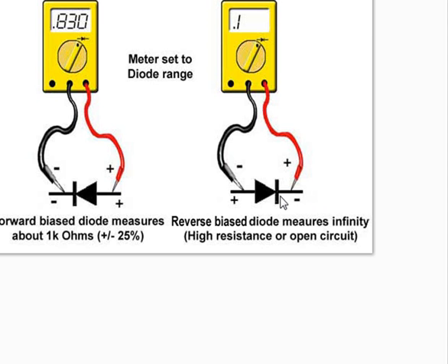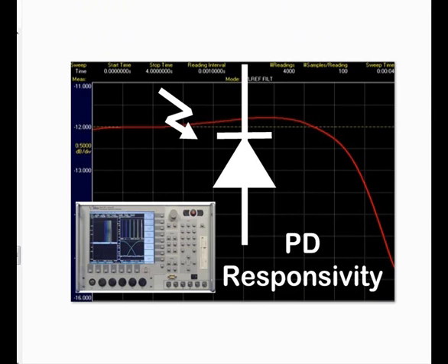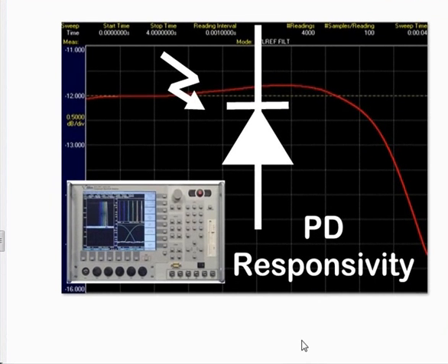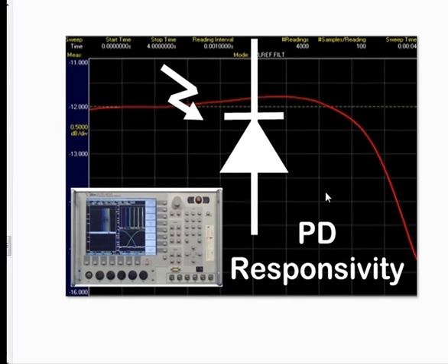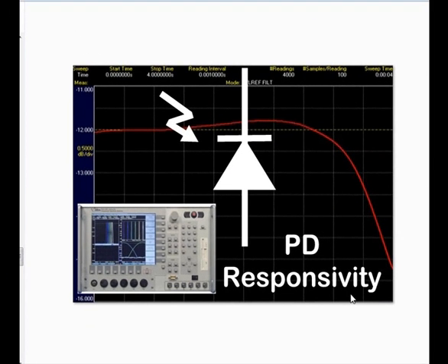And that is how you will try to differentiate between a photodiode, an infrared diode and an LED. It is a little tricky, but this is the best way of checking the photodiode. And you can see from the graph here, when the light falls, it behaves like a resistor conducting heavily in the reverse bias condition. That means current can flow from here to here.